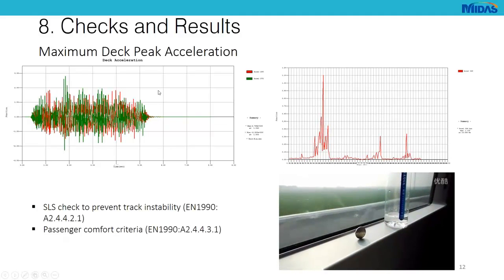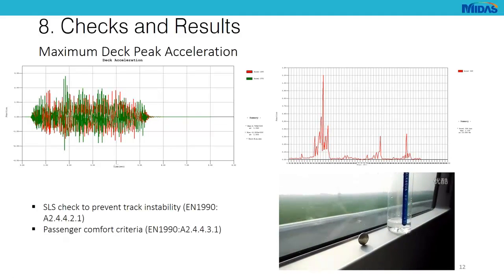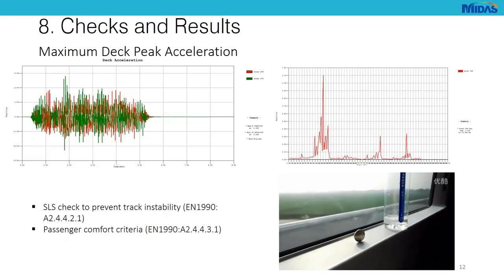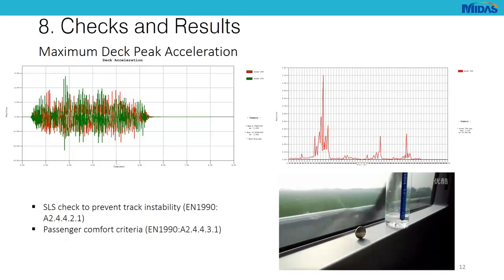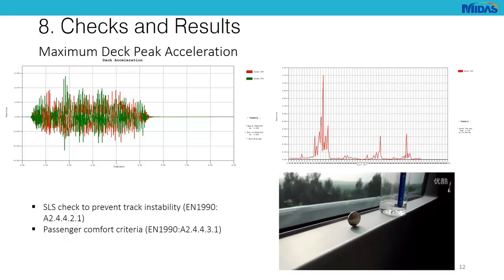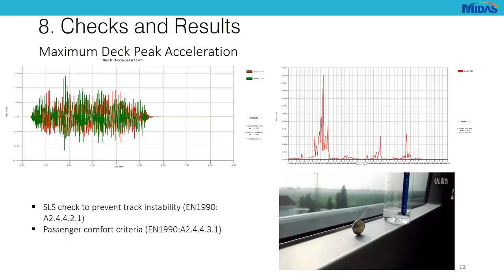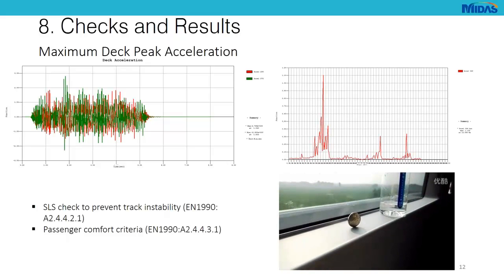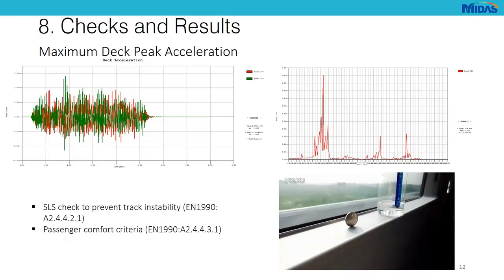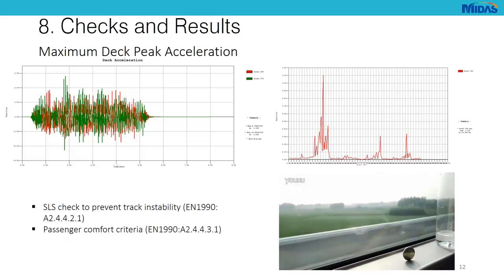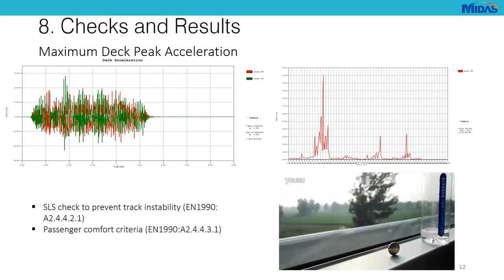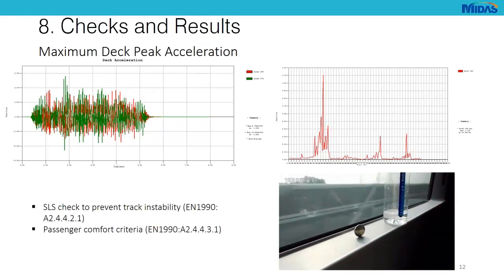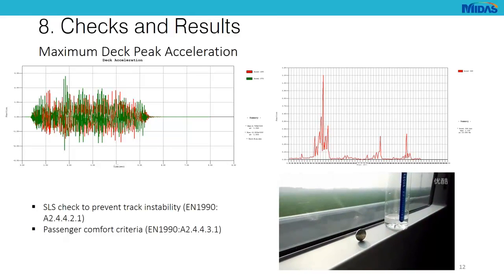And then once we've made sure that the acceleration value is not passed, so the requirement is fulfilled, we are also interested in making sure that the excitation applied to the structure coming from the train load does not match the resonance of the structure. Does not match the vibration properties of the structure. So we don't want to have the same frequency as the frequency of the structure.